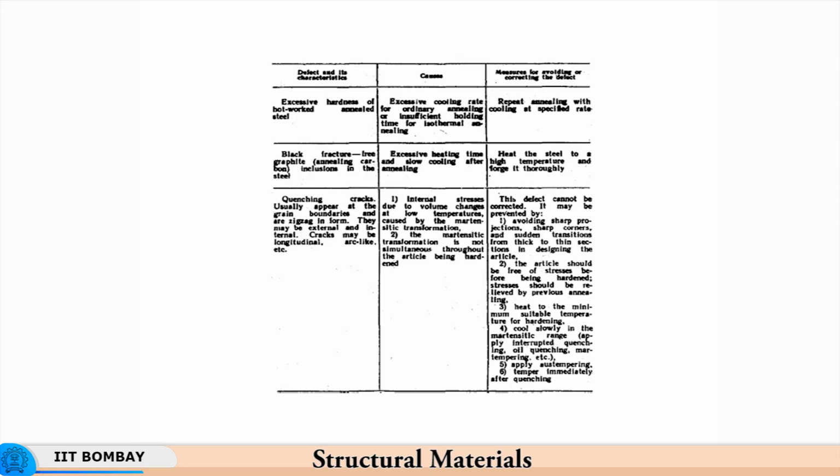In fact, brittleness is an outcome of quenching and martensite generation, and if you do not temper it, the product will tend to behave brittle. Although it may be hard, it might not have cracked, but still it will be brittle on the surface. So, a small impact can generate these cracks and render it useless. So, it is important to immediately temper it after quenching.